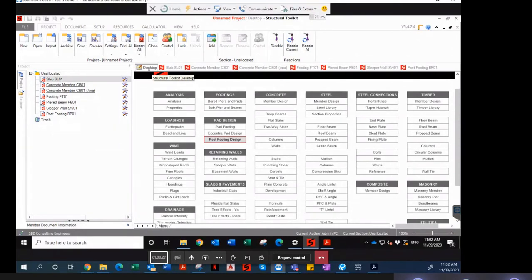So if you're using all the available types of bracing like 30 by 1.2, 25 by 0.8, all those bracings could be on the side as a drop down, and you can just choose from the drop down, and it gives you the areas and everything, and gives you the capacity.